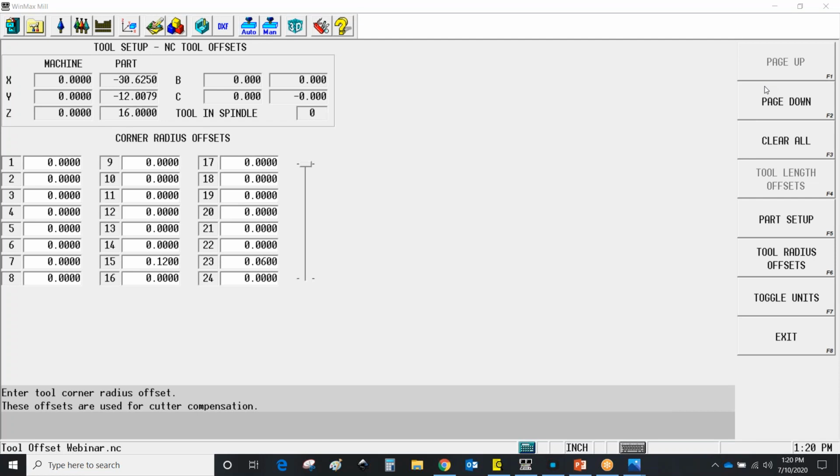Turning on and off the tool length offset, that's a big one for a lot of shops that don't do NC all the time, or they have some less experienced operators. That means you only have to focus in one area for tool length, and that's on your tool offset page or tool setup page. Stripping that G43 out of the program is another one.